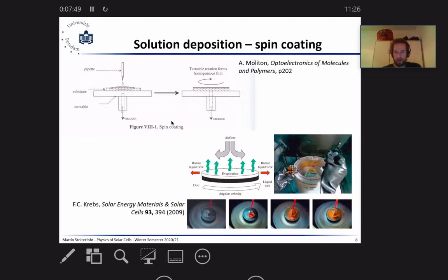So as most of you know, a solution is mixed together, and then, as illustrated here, a drop of the material in solution is put on a transparent conductive oxide, and a film is produced by spin coating. That leads to a rapid evaporation of the solvent with this fast spinning, and the film crystallizes.